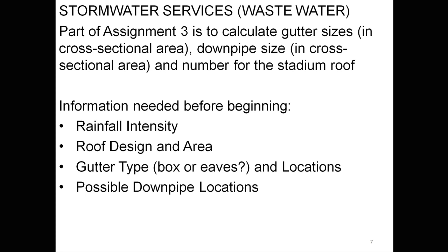And then the roof design and area is what we've looked at, what I've spoken about. So for the purposes of assignment 3, what I'd like you guys to do is just to work out the plan area, rather than the surface area. So of course, with the surface area, you've got to take into account the area of every single different slope, be it curved or flat or sloping or a parabolic, hyperboloid, or what have you. But for the purposes of this exercise, we will just take the plan area of the roof. So what you're looking down from the top, that area, and I'll explain a bit more about that.